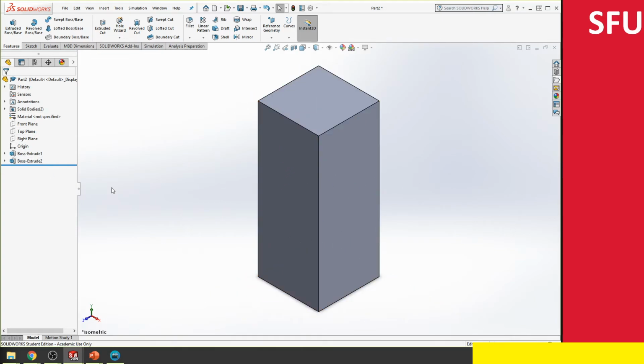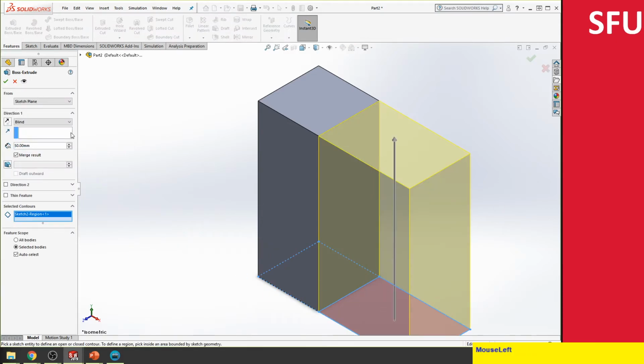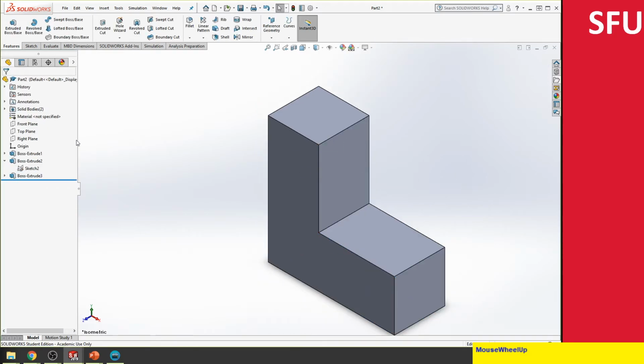Notice that my figure went away. It's not gone too far. It's actually hidden, it goes inside this object. So what I'm going to do is use this drop down here to open up this object, click on sketch, and do extrude again. Now I'm going to select this region. This height I probably want to be about 20, and then say OK. This basically creates the shape. You can compare it with the previous example that we had, and convince yourself that both of them look identical.